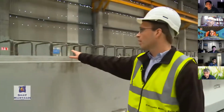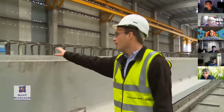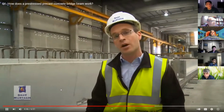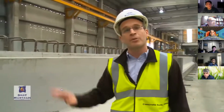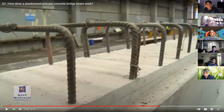Finally, you'll notice as well, we've got shear links in the beam. The shear links we use in the bridge beam would really not be substantially different from what you may be accustomed to for reinforced concrete bridge beam design. So again, a pre-stressed concrete bridge beam would also make provision for shear design, shear reinforcement. This reinforcing, in many cases, I have seen it to be epoxy coated. This makes sense to you guys?